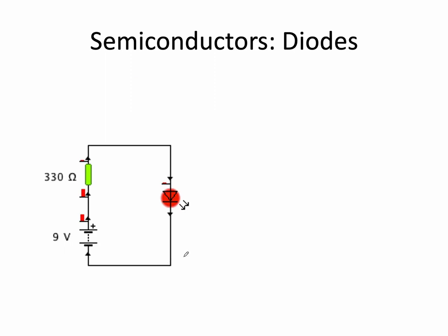You can actually make the electron jumps. So we talked about how you can dope in different ways. When the electron goes from the N-type to the P-type, you can actually make the gap large enough, in other words, the hole deep enough, so when the electron goes from the N to the P, it actually falls into the hole. And you might remember that from chemistry. When electrons went from one subshell to another, they actually emitted photons. Well, if you make the jump large enough, you can emit light. And what kind of diode is that? It's called a light-emitting diode, which is such a mouthful that we usually just call them LEDs.